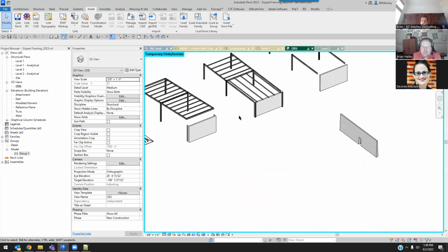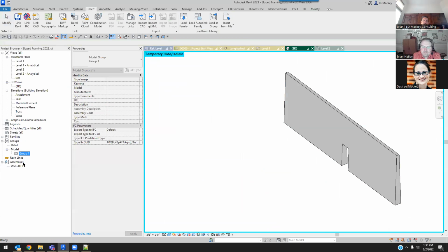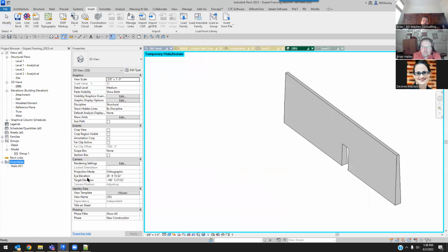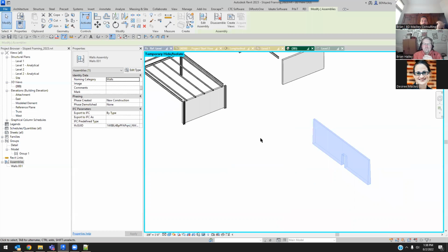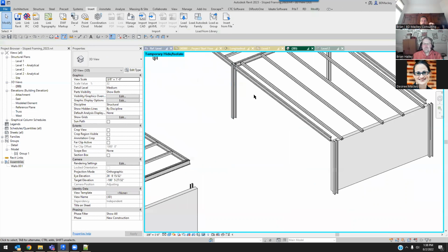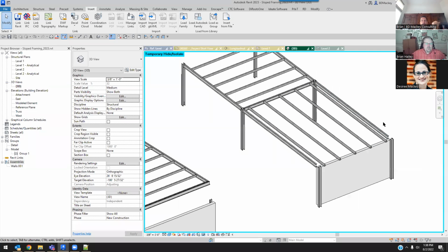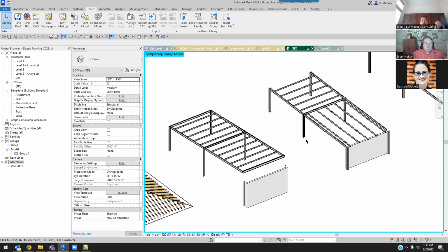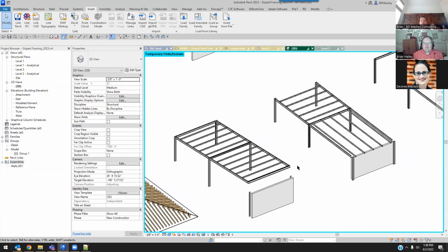Yeah. The problem with an assembly is you can create assemblies, and the whole reason this was part of the Autodesk back in, I think it was Revit 16, they were trying to come out with like Revit for contractors. And theoretically, an assembly can be used like a group, and it's great. I've used assemblies. I have one client using assemblies where instead of doing a group, we modeled all the rebar and the concrete column, how it tied into the footing, etc., and copied it around. The downside of assemblies is when it changed, I edited the assembly, changed the rebar, and said, oh, this changed from all the other assemblies.